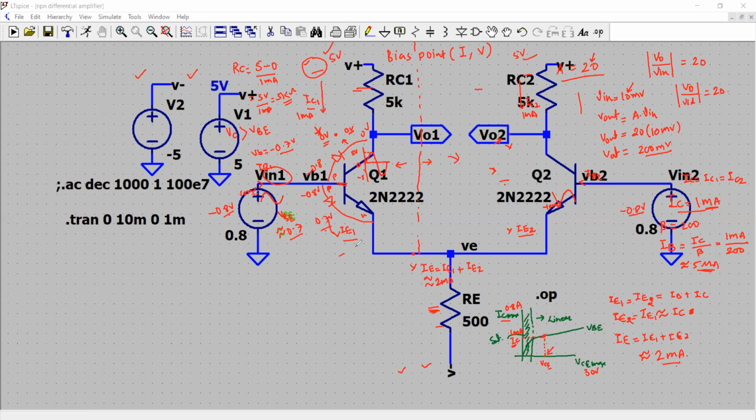And the difference should be about 0.7 volt right here. So if I apply minus 1.5 actually, let me check here. Right. So I have, let's say, minus 0.8 at the P, and at the N, I would say minus 1.5 volts right here.